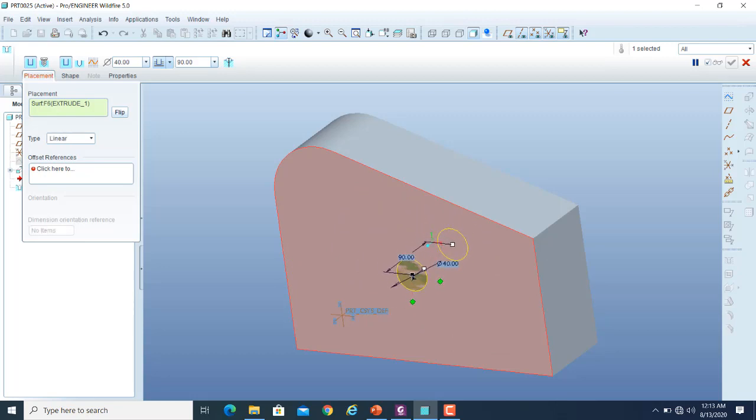How to fix a point on that particular surface? For that we will use these references, these green pick boxes. So hold these grippers, and these grippers will basically be used to dimension this hole in the vertical direction and in the horizontal direction. Because we have a plane surface over here, if you want to define any point along that plane, you need to define two axes, horizontal and vertical, and you have to define their dimensions.